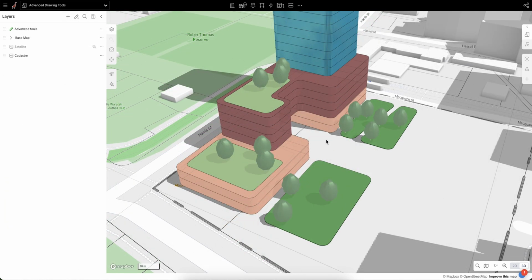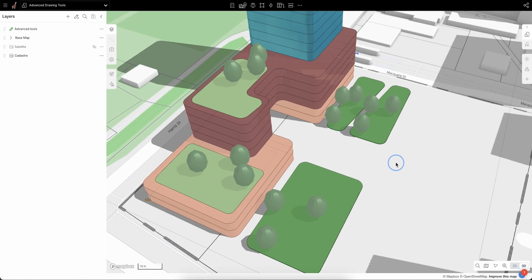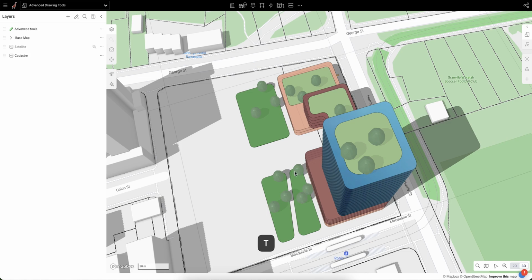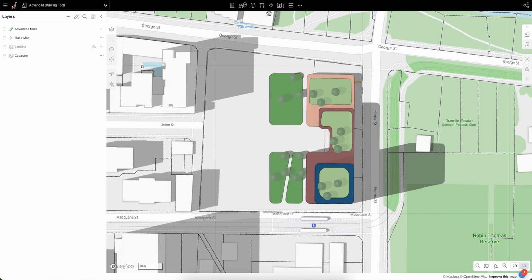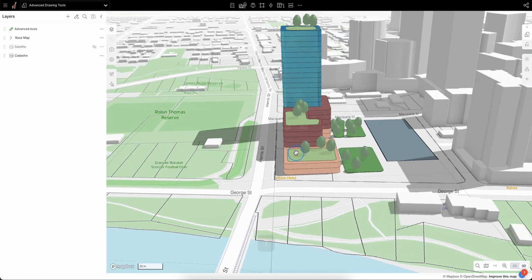The next feature I'm going to talk to is the Eyedropper tool, or match properties as you might otherwise know it. And the way I'm going to demonstrate that is I'll just navigate into 2D mode, so T on my keyboard. And what I'm going to do is just grab the basic rectangle up the top here, draw my rectangle, toggle back into 3D mode.